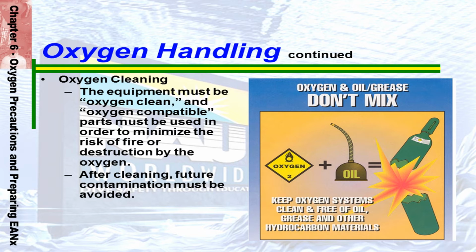Care must also be taken to avoid sources of ignition, the third side of the fire triangle. A sudden increase in system pressure could elevate the temperature in the system sufficiently to cause ignition of any contaminants. Valves should be opened slowly to prevent a sudden increase in pressure with an accompanying rapid temperature rise. Even a static spark from a rug or opening a Velcro closure could cause ignition in a pure oxygen environment.